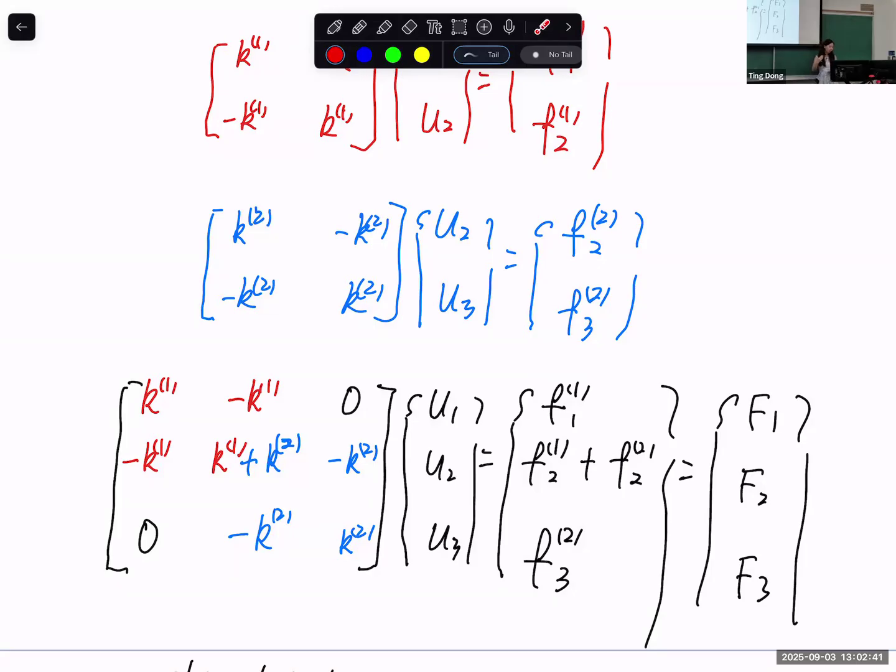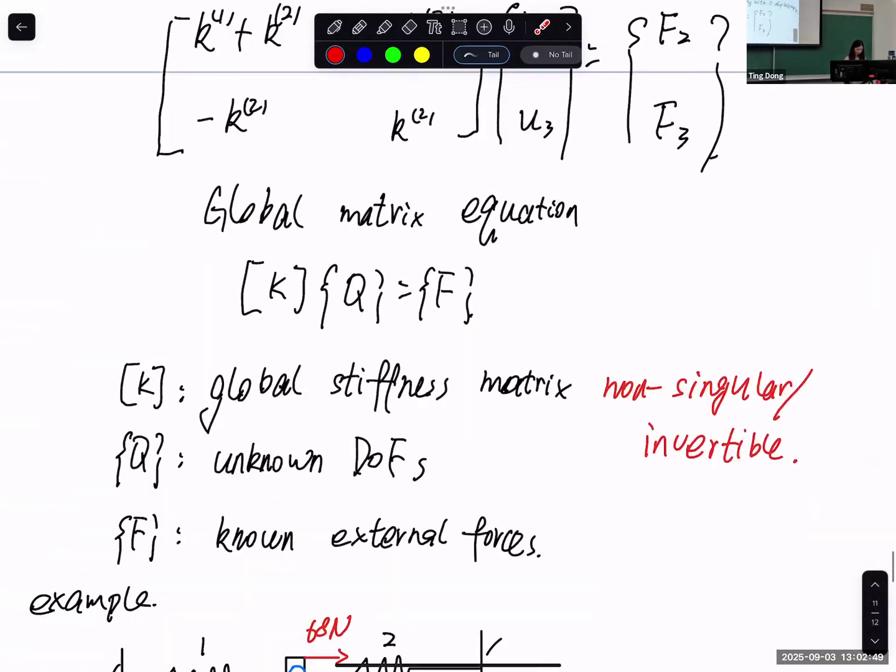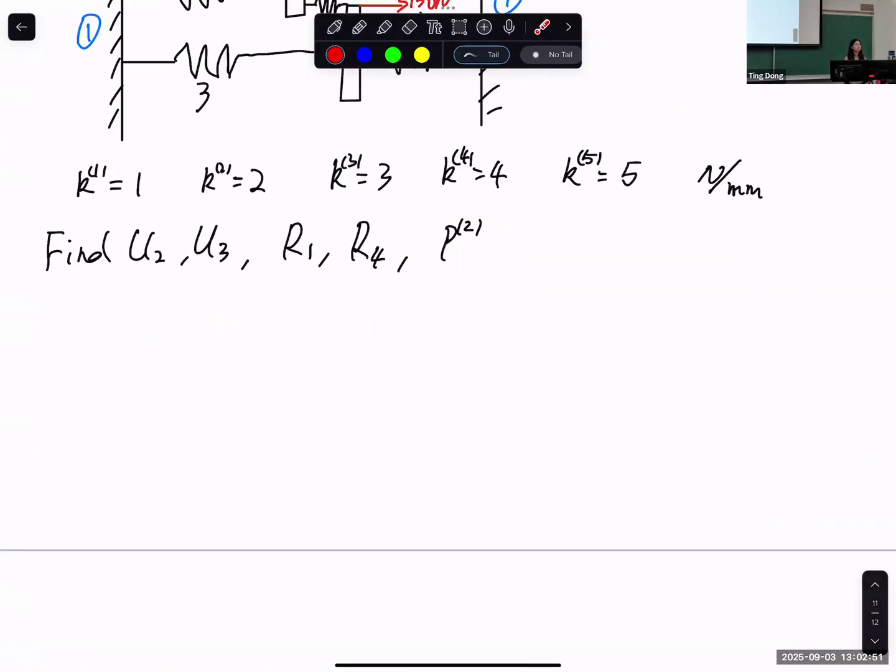So now our job is how to find this 4 by 4 matrix. How to write this 4 by 4 matrix. In your homework and in the exam, you can write this 4 by 4 matrix directly, or you can even have the 2 by 2 matrix directly. Just write the matrix after applying boundary conditions. That is fine. But since this is our first example problem, I'm trying not to skip any steps to make it as clear as possible. I will write the K matrix for each element and show you how to assemble them into a big 4 by 4 matrix.